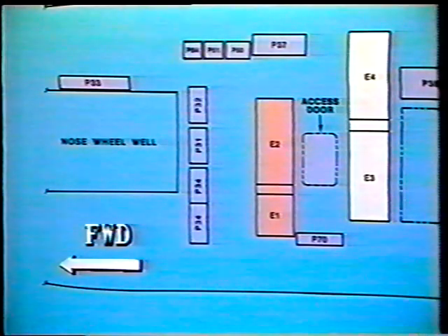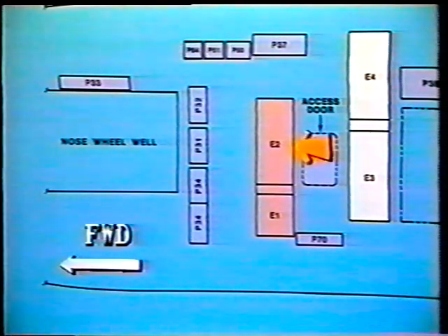The symbol generators are mounted on the E2 rack in the main equipment center. A test switch, located on the front of each symbol generator, provides a test pattern for checking on the EADI and EHSI to check system performance. Next to the test switch, a reset switch is used to reset the byte fault memory.